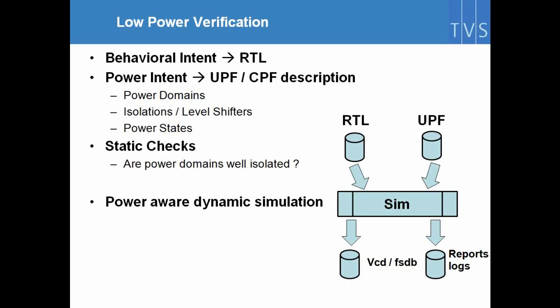So we have static checks that are provided by some tools, which are more structural checks. We then have the ability to run power-aware simulations, which take both the RTL and the UPF, and you simulate your design with more information than just 0 and 1, which is what you do in RTL.